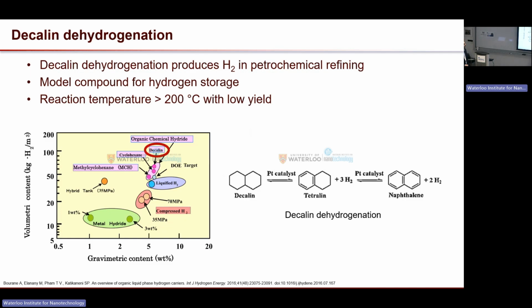So what you have to do is take this out. You have to condense out the condensables and then reheat and inject it back, and you take out the hydrogen. So that's a very equipment intensive and energy intensive process. So they wanted a membrane that can operate under the reaction conditions and just bleed out the hydrogen.